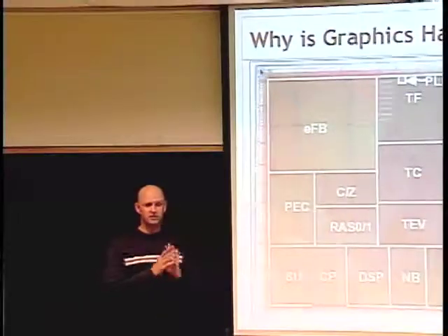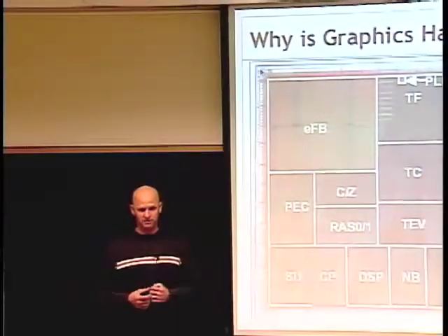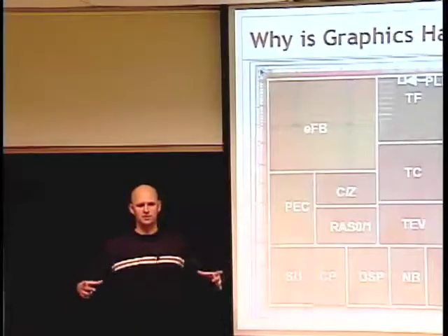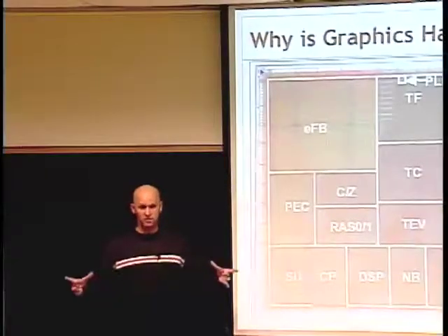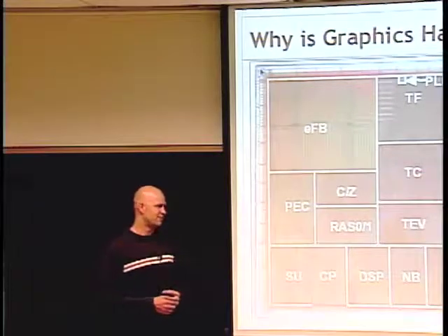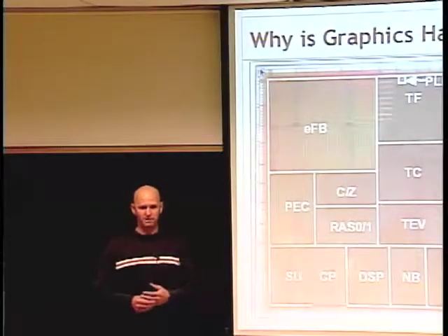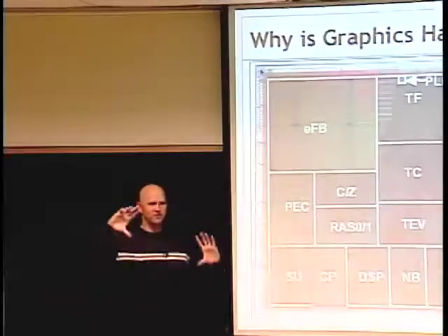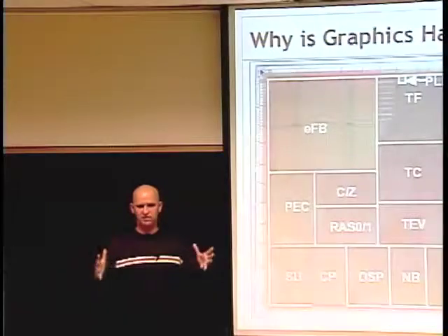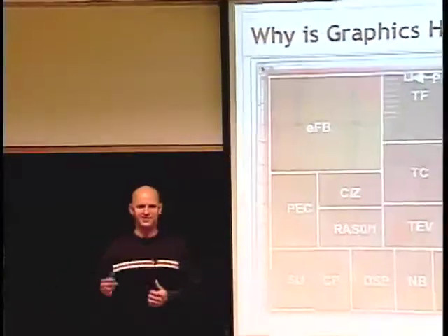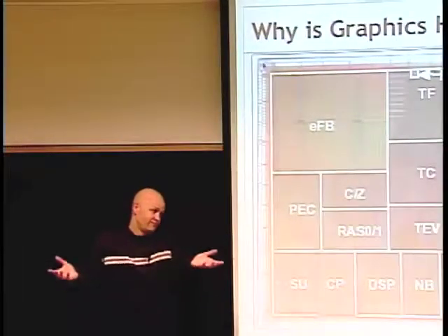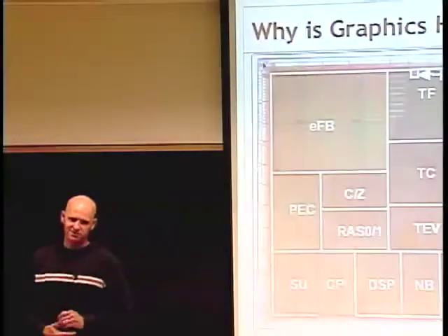That being said, there's a lot of storage on the chip. I know there's 6 megabytes of registers alone on the NVIDIA compute units. 6 megabytes. That's a lot for registers, right? So they're just using it a different way, and they don't keep the whole frame buffer. Because I guess part of the problem is you say, oh, frame buffer, it's just a TV screen. But frame buffers are deep. They have lots of information associated with them. Their use is growing just like the rest of the graphics pipeline. It's not like they're just storing one color and one depth. They're storing lots of things per pixel often. Good question. I hope you ask the people that come to visit.